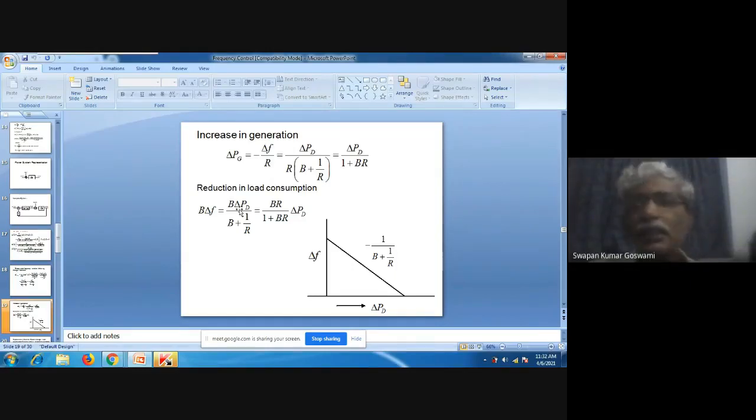Immediately after that, as I explained, the load will appear as an impedance to the system. As the impedance has been changed, what is happening? There is more current delivered by the system to the load. So the output torque on the generator increases. Input torque remains the same. So there is some decelerating force acting on the generator.